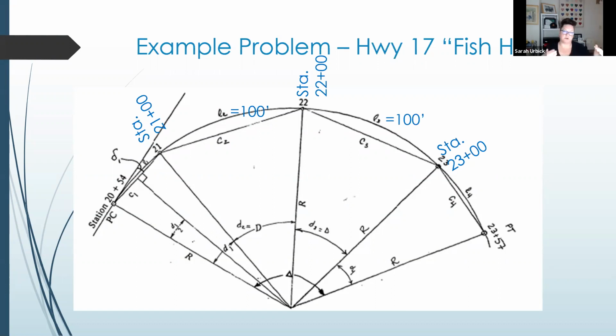Railways tend to use the chord length. However, here's the interesting thing. When you get to small enough angles or a long enough radius, that difference becomes very minimal, out to the hundredths, if not thousandths of a foot.